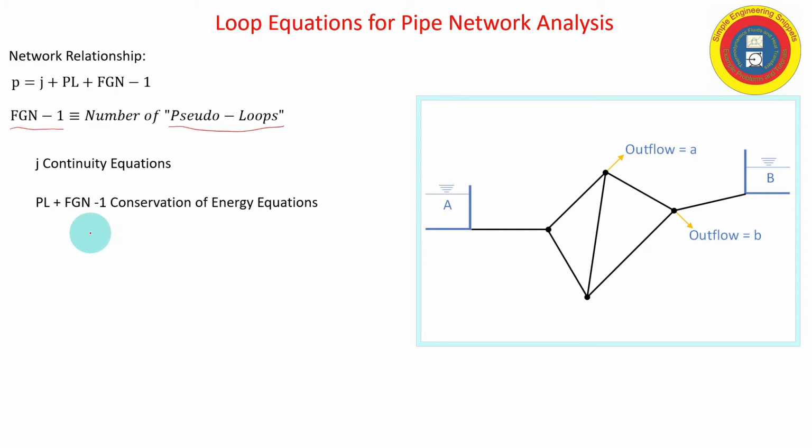It is that we're going to be applying conservation of energy around the loop. And if my end point is the same as my start point, then the change in head is going to be equal to 0. So when I march around a loop, for example, say this left triangle, and I do assume a direction for that cycle, I will march around and apply conservation of energy, and then I will set that equal to 0.